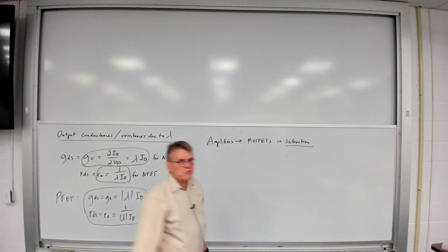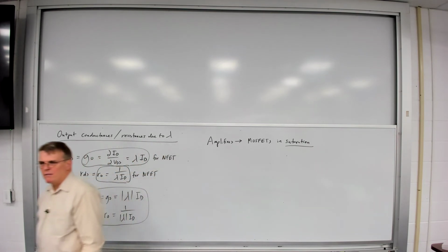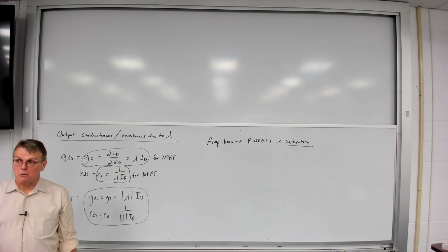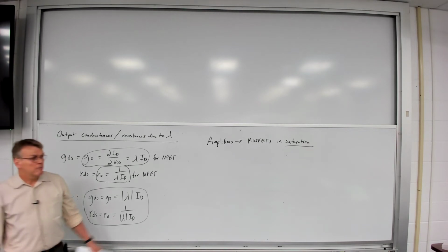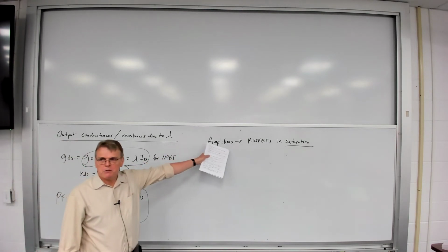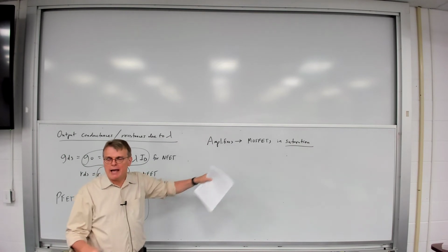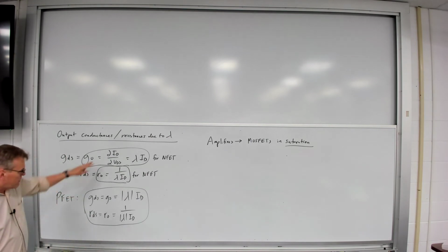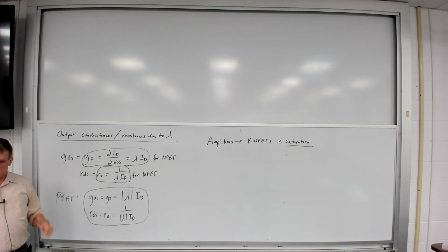We do not use triode or ohmic region operation. That is important when we talk about digitals, and we'll get to digital circuits later on. But for high-gain amplifiers, when we're doing analog design, saturation is where we want to be. And so as I said before, these are going to become critical when we start getting to that point.